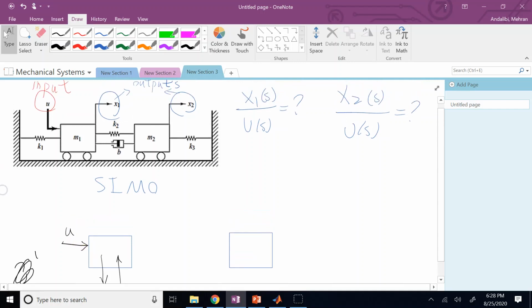Then if the motion on the right side is x1, the motion on the left side of this spring, if you focus on this spring, the right side of it moves with x1, the left side of it does not move. So the difference between the displacements is x1 minus 0, and since this object moves with x1 to the right, the spring has to be stretched, so it will apply a backward force to the left.